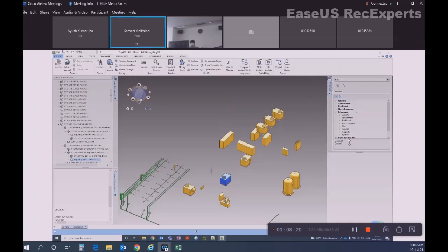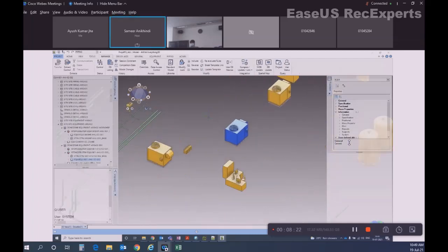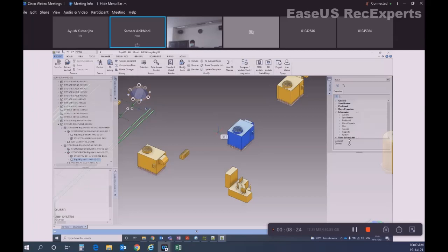For example, I will tell you the ID command. ID is in AutoCAD, you know what the ID command does? It will give you the coordinates of a particular point. So ID is an in-canvas command, press enter. It will ask you to select a point. It will give you different snap points, but it is snapping to the origin.